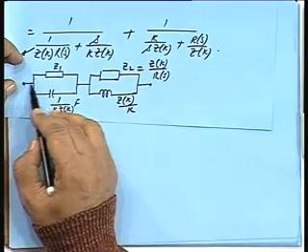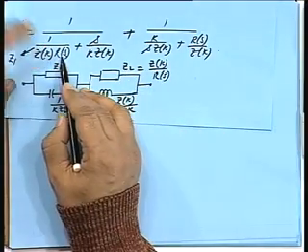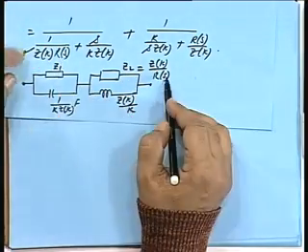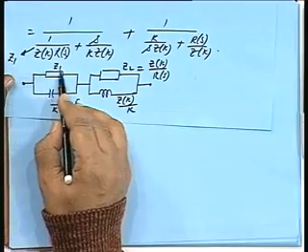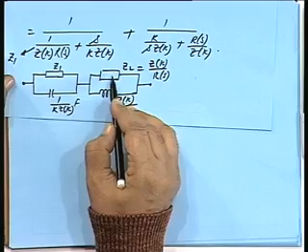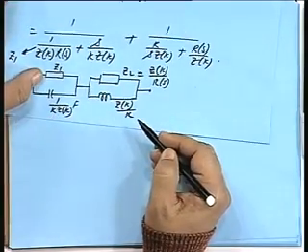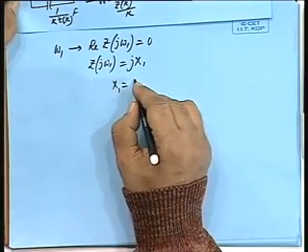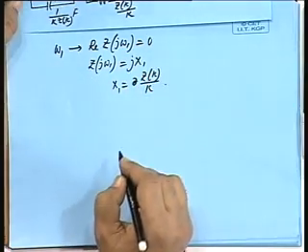Okay. Then the current will flow through this, and then Z2 is Z(k) by R(s). If R(s) is having a 0 at omega 1, then 1 by R(s) will be having a pole. So, if this is 0 impedance, then this will be infinite impedance. So, the current will be made to pass through this short circuit, 0 impedance, and then going through this, because this is open circuit. So, it will be appearing to be this inductance. So, Z(k) by k, we started off with Z(k) by k is equal to X1. This was our starting point.